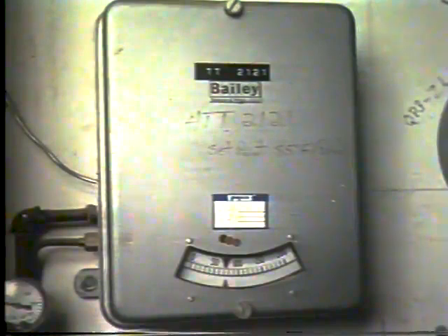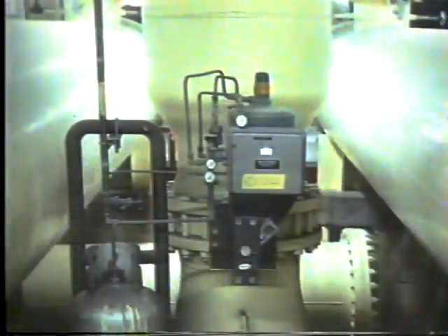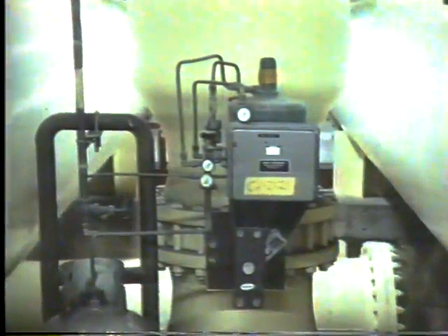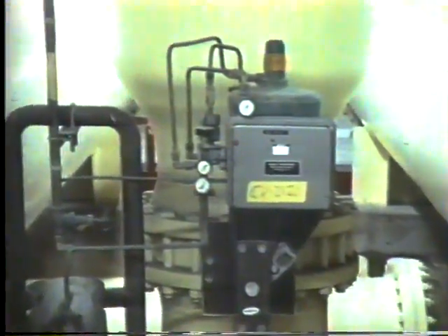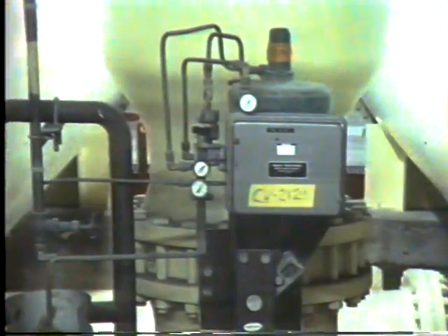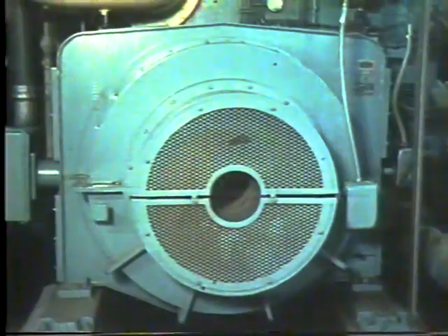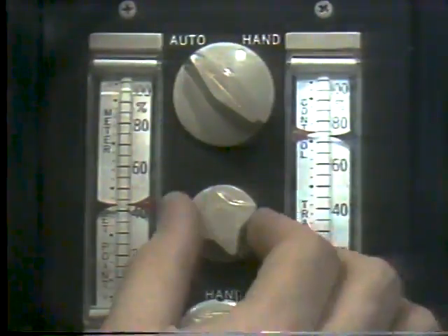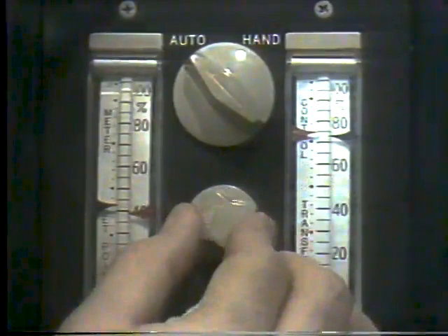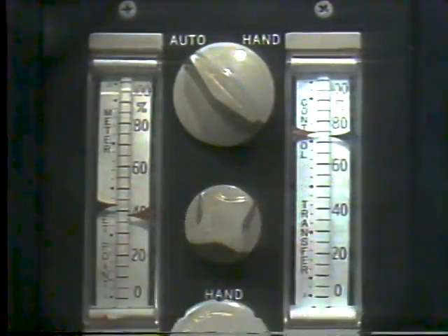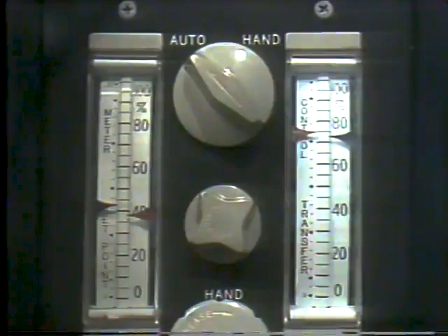Next, you put the system in automatic and make a load change. A load change is simply varying something in the system that will cause the controlled variable to change. You can generate load changes several ways. You can manually operate a control valve to cause the controlled variable to deviate from set point. You can turn some equipment on or perhaps off. Or you can simply change set point. Usually a set point change of 5% or so is sufficient to simulate a load change.